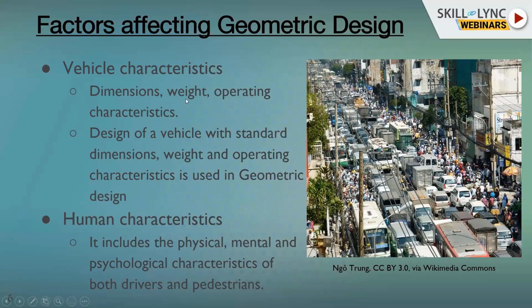See, can anyone imagine how the weight of the vehicle can affect the horizontal or the geometric design? The weight of the vehicle will affect the total load the pavement should take, right? So the pavement engineers will do certain calculations, and they'll use some crust thickness.